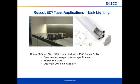Perhaps a little bit more utilitarian application might be some task lighting. This is a shot of a kitchen scene, and tucked up behind the cabinetry overhead is a very thin strip of the RoscoLED static white tape in a corner profile. You can see it provides a nice little wash of task lighting down onto the work surface, in this case, a cooktop. It can be outfitted with whatever color static white tape the end user desires, and you can also include a 0 to 10 volt dimming control if that's desired.